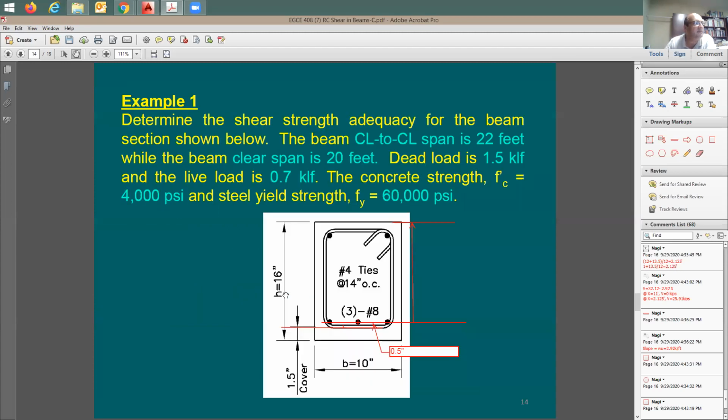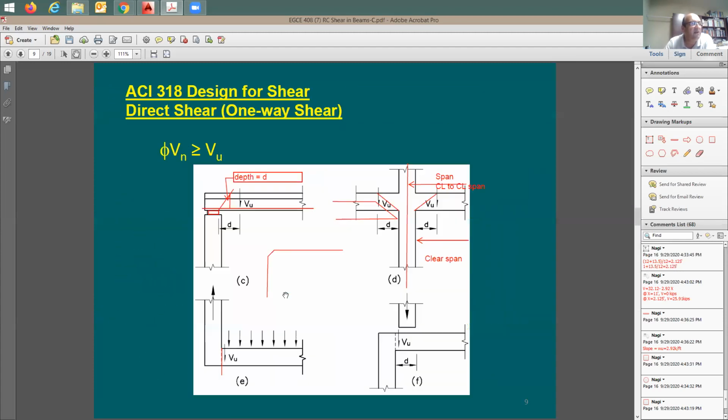They say because if shear failure is going to happen, it is not going to happen right at the center of the support. If shear is going to happen, it's going to happen in reality at a distance away from support. So just imagine this is the beam before it fails, right? You start to put some loads from the top like this. You start to push it down.